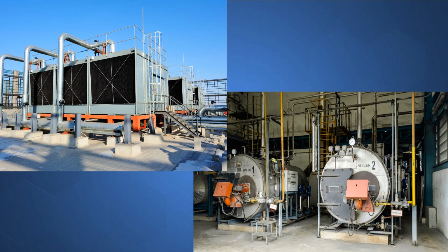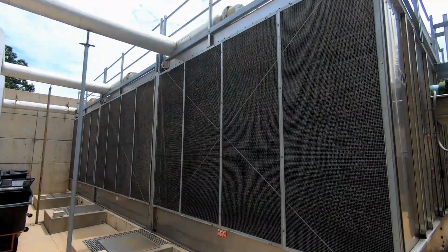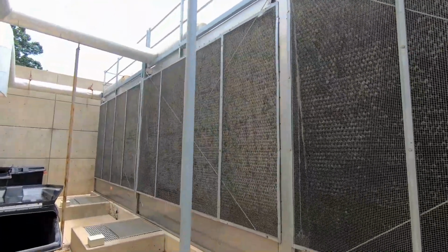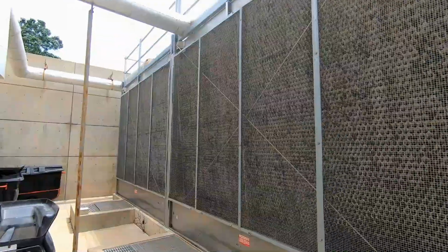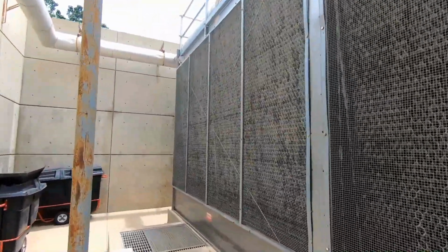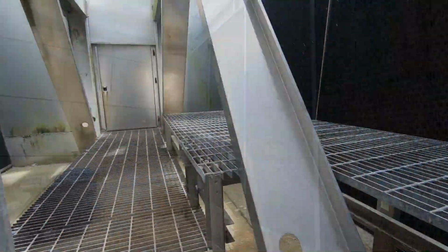through evaporation and/or freezing. When cooling a building, there are system components used to remove heat from the air being drawn in, and eventually that heat and energy are released by the cooling tower into the atmosphere. We are using a combination of the fans either blowing air through or drawing air across the fill to remove the heat from the water and dropping the temperature of that water roughly 7 to 10 degrees based on the design of the cooling tower.